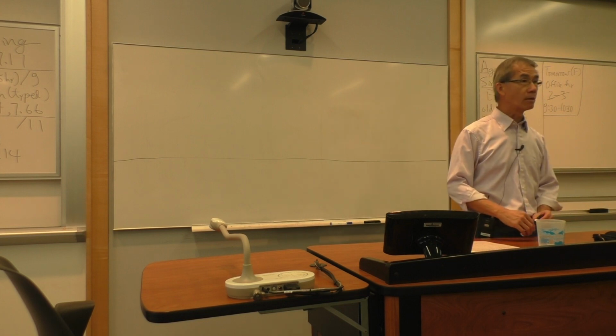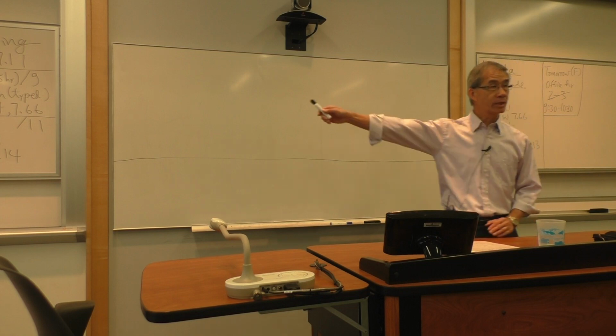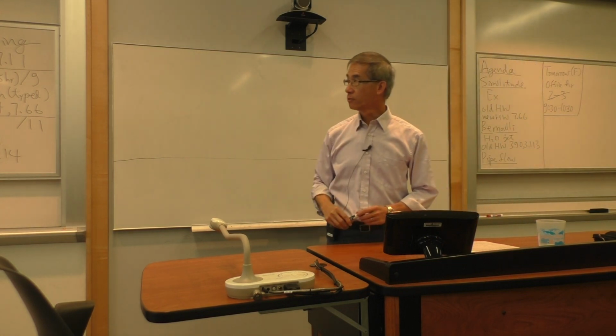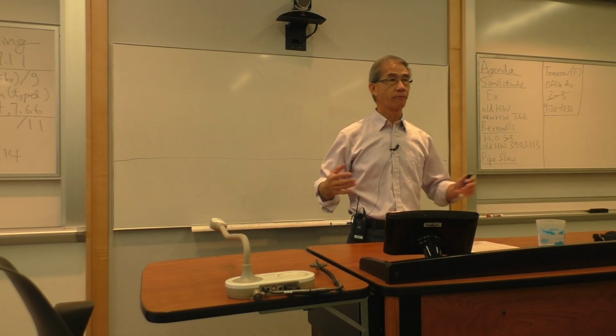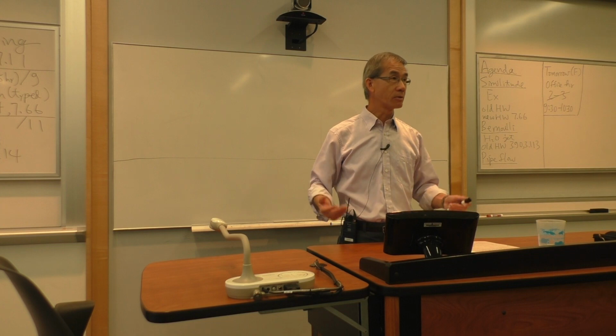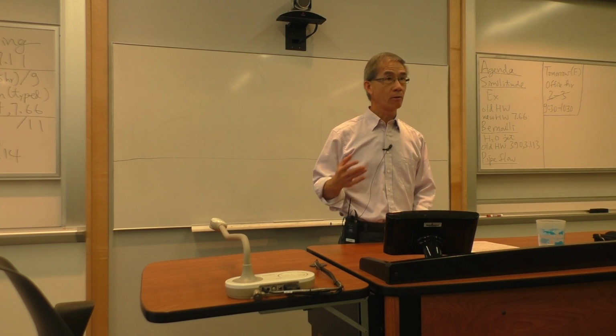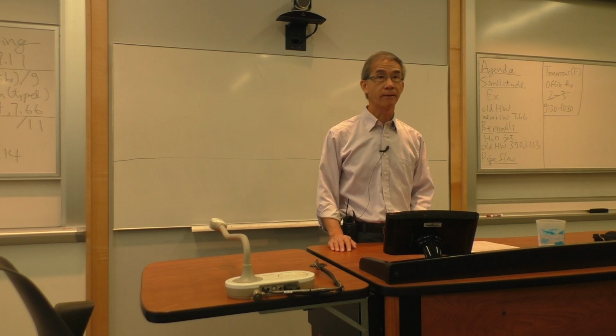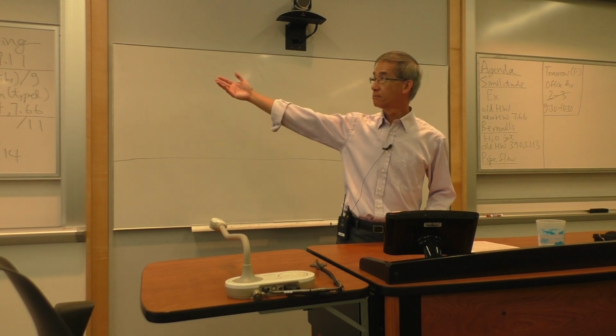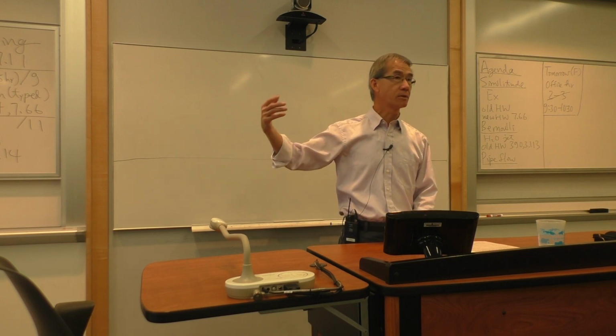So any question before I start? A high-level recap is shown there. We will refer to that throughout this lecture. So pipe flow, we went through a lot of solid and dense material to come up with a pi term. And now I hope you're all very comfortable with what is called a pressure coefficient. Any question on that? Dimensionless, delta p over half rho v squared, the 1/2 is not from dimensional analysis, it's from convention. And it's a function of Reynolds number, length to diameter, roughness.